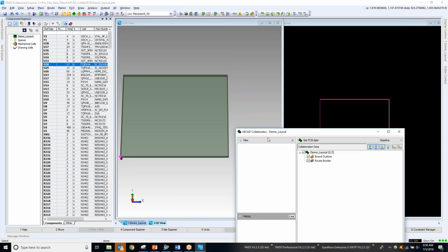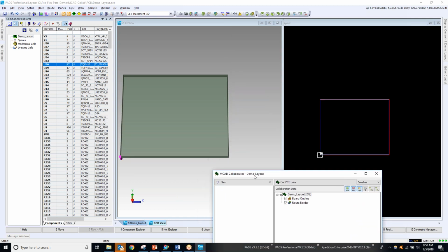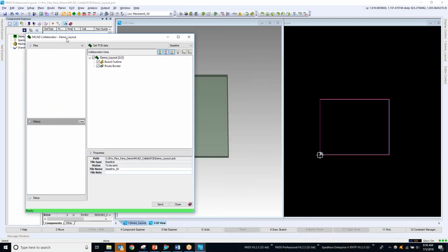Okay, so right now, we don't really have anything to change from the eCAD world or the MCAD world. We've just finished our schematic, for example, and now we're trying to transition into layout. And what we want to do first is understand the board outline that the mechanical team has come up with due to spacing requirements, due to what they are designing for the enclosure, and where all those mounting holes need to be set up.